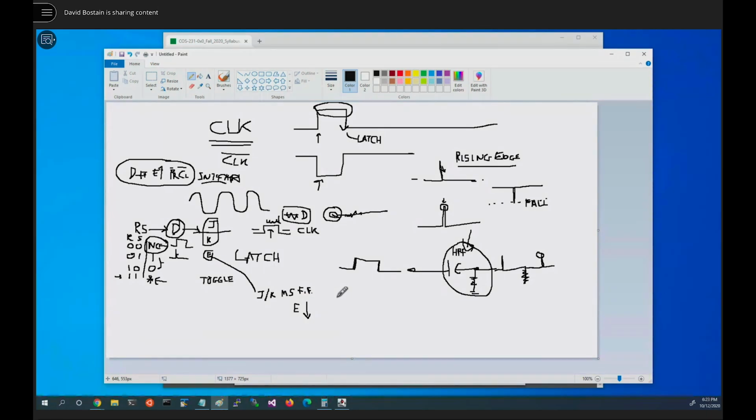But what you would really imagine it to do, if you were showing what the clock itself is doing, is that it would show you an inverted signal. But because it's a two-stage clock, the actual external pin maybe shouldn't be labeled that way. Because in one case, it is triggering something that happens on a falling edge sometime later. But on the other hand, the actual clock it's changing is a level-triggered, high-going clock. So we actually have to look at the diagram I gave you to study and see if we can understand what's going on with that.